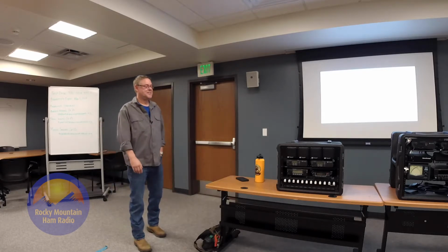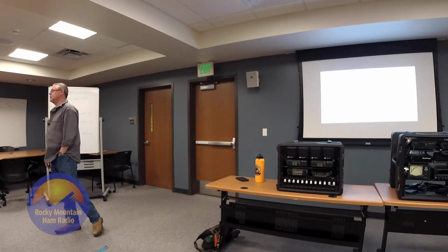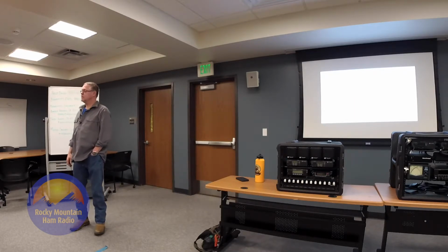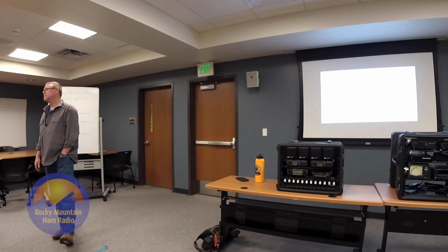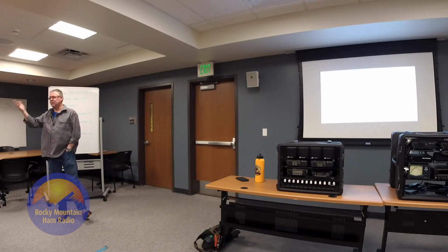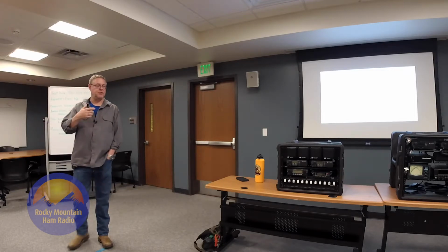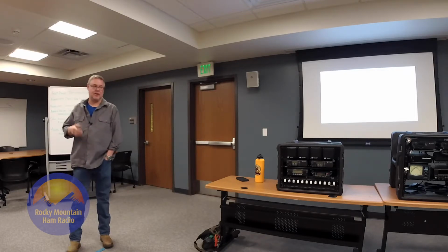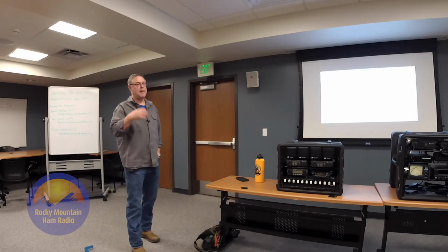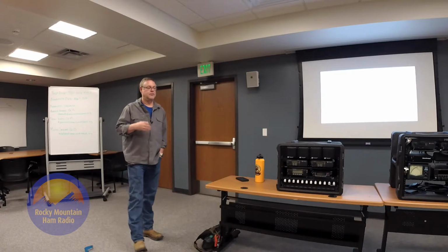Yeah, I mean, the problem basically is if you're trying to run 100 watts out of your HF rig, you pretty much have to have pretty good power, and short leads and thick wires, because if you have any losses at all, suddenly you're down to 11 volts and the radio starts cutting out. Exactly. In a situation like that, if you needed 14 volts and you only had 6 or 8 volts available to you, and you used one of those for an HF rig that's spitting out 50% duty cycle at 100 watts, it's not going to work. It's not going to work unless the thing's backed up by an alternator in your car or something like that. Those things aren't efficient enough to do that.